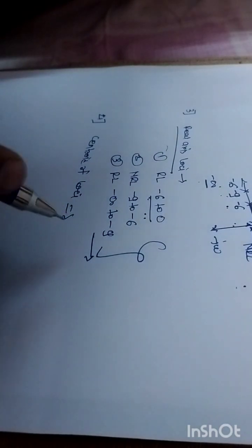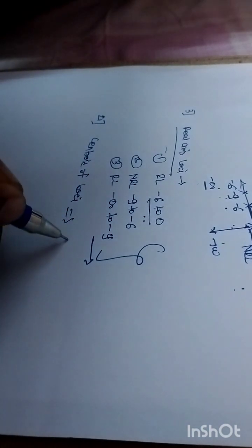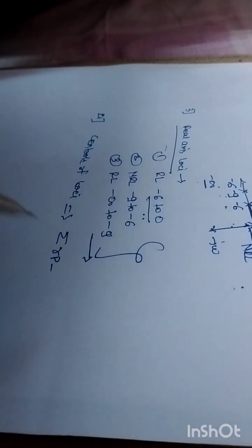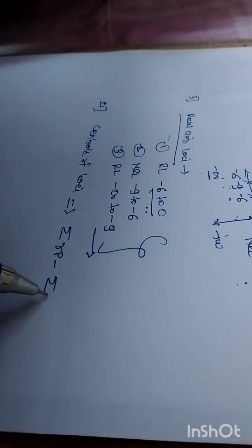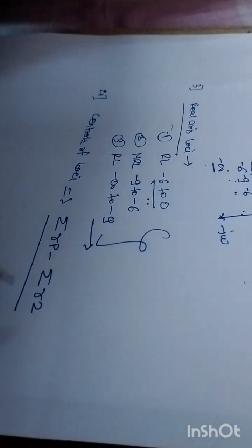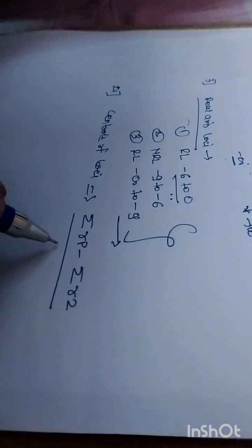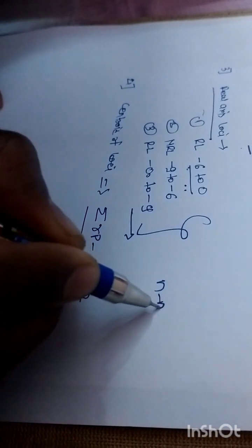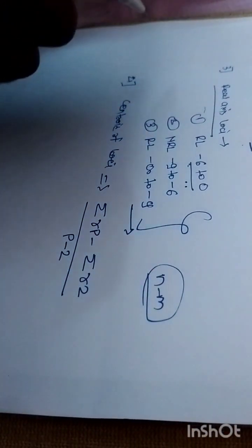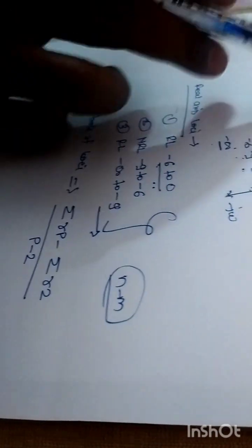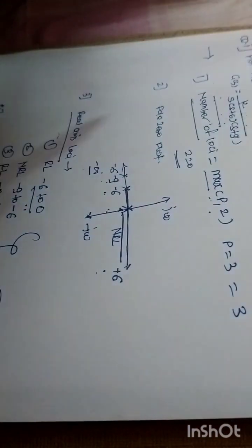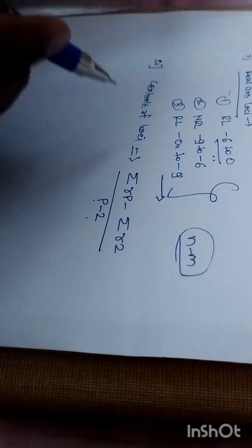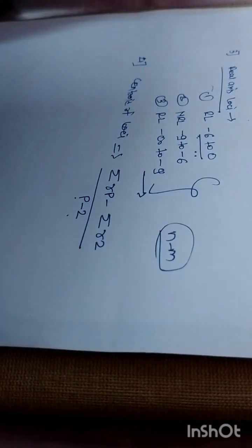So we have one standard formula for this centroid. That formula is the summation of real part of poles minus the summation of real part of zeros, divided by its denominator. The denominator will be P minus Z, or in some books it is given as N minus M. Different notations are used to indicate these two desired quantities, poles and zeros, right? So here what is denoted? P minus Z, right? So we have the real poles as well as the imaginary poles.